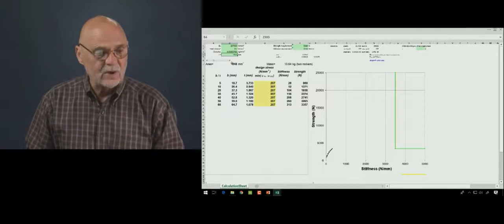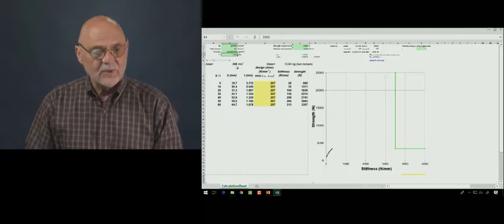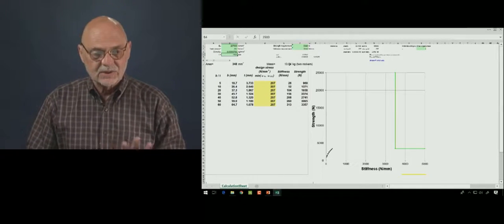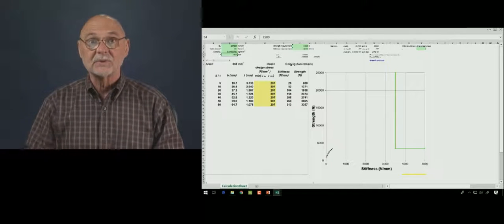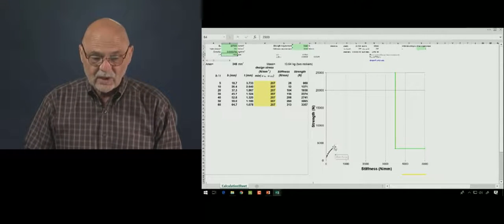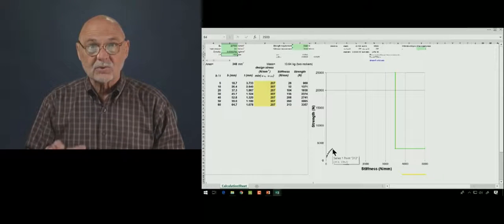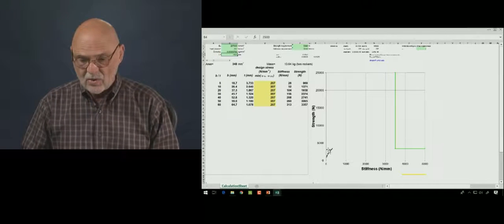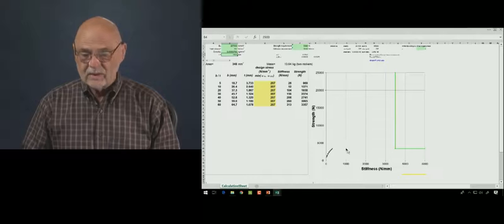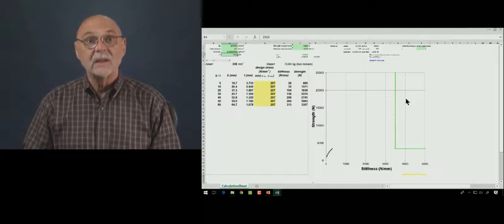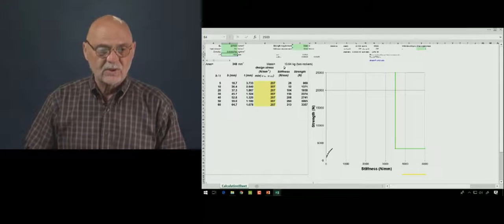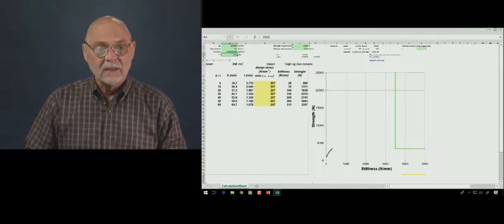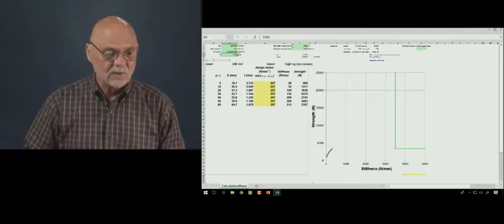And in that case, we have a cross-sectional area of about 348, and the mass for that steel beam is about 13.6 kilograms. Okay, but we're only meeting one requirement. We're only meeting the strength requirement, and we have a long way to go before we get into this zone to additionally meet the stiffness requirement. Okay, so just remember this: 13.64 thick wall meets the strength requirement.